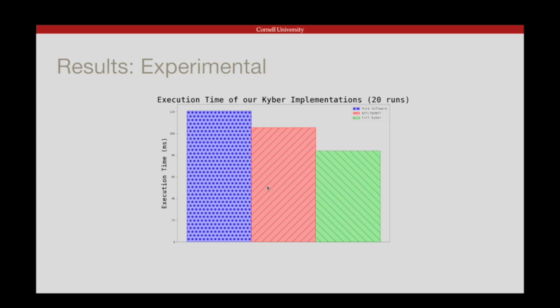This is not only due to the fact that the ARM core is running at a higher frequency than the FPGA hardware, allowing it to perform more operations in a given time, but also that Kyber overall has many different types of operations, or kernels, it needs to do as part of the overall algorithm. With each operation or kernel requiring different hardware, it can be difficult to reuse hardware across the entire application, resulting in fewer available resources and less ability to replicate hardware to achieve parallelism.